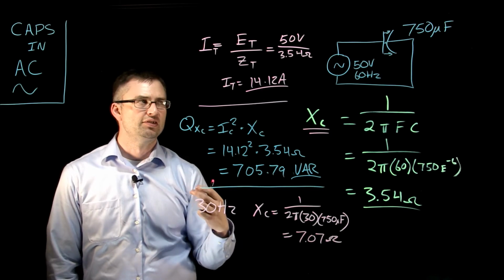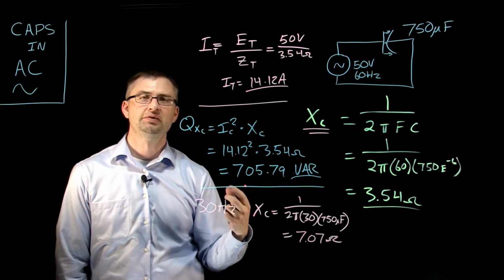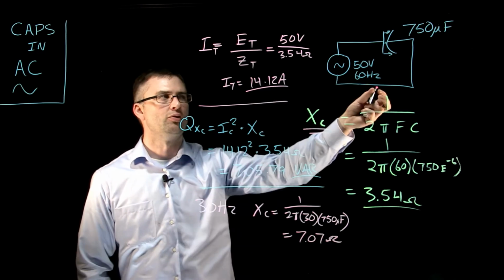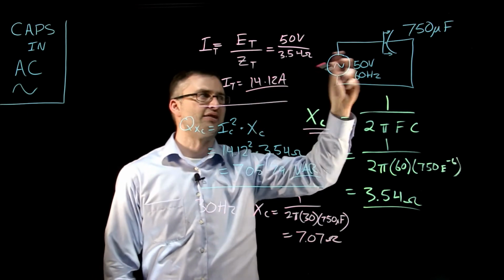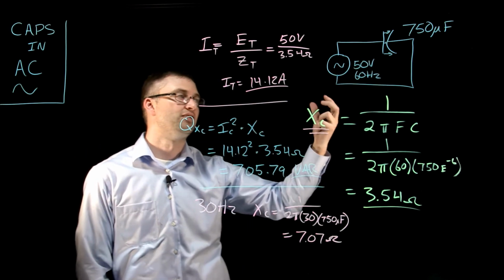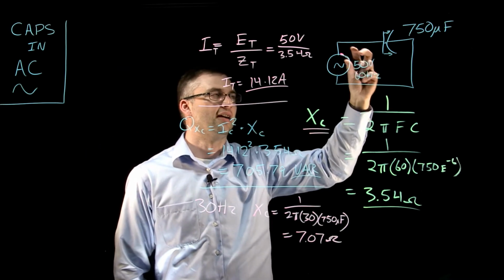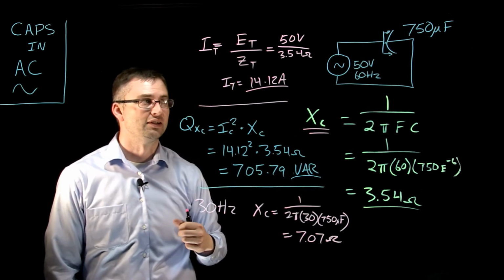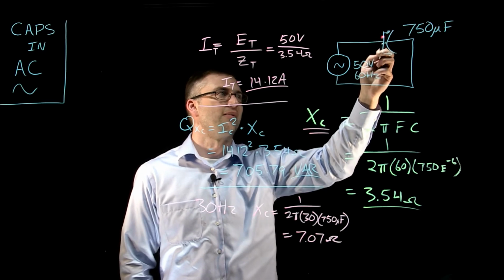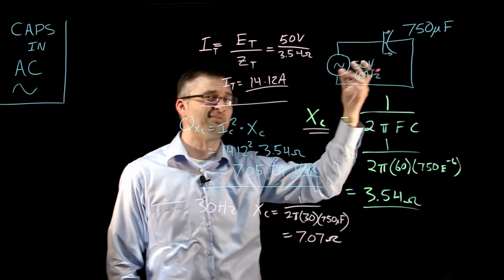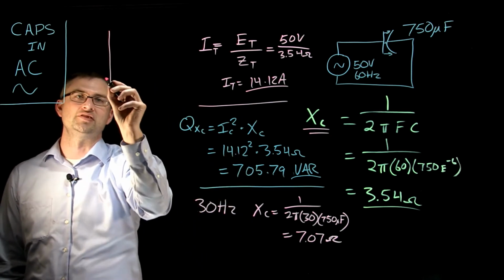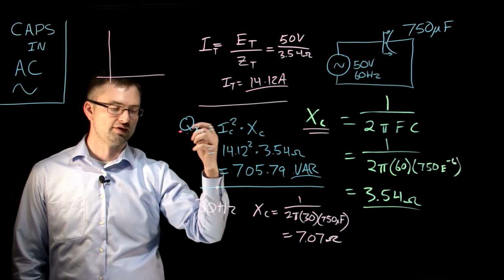So it could be said that when you start to increase frequency more and more and more, current is very easily stored and returned off of that plate, and the faster you do it, the less opposition to the change of voltage, and therefore the increased amount of current that can flow in that circuit is going to go up. And there'll be less and less ohmic value from that capacitor when the frequency goes up, because it's very easy for it to charge at first, and it starts to become more difficult to charge once the voltage starts to equalize with the source.